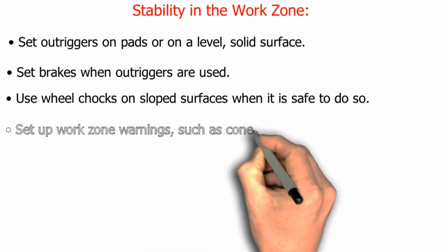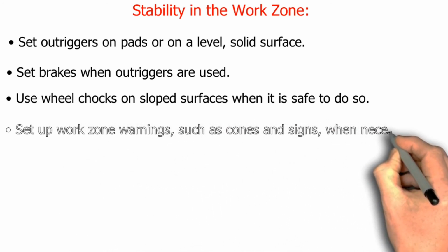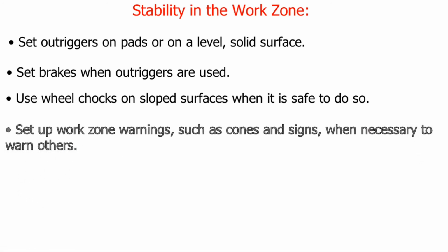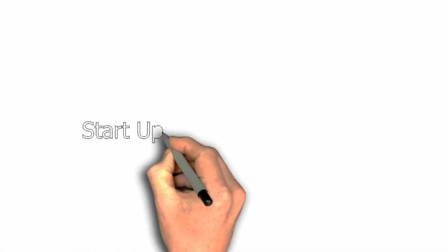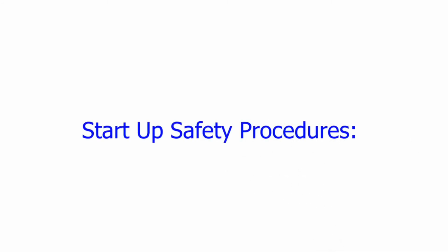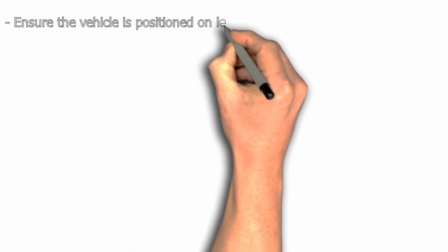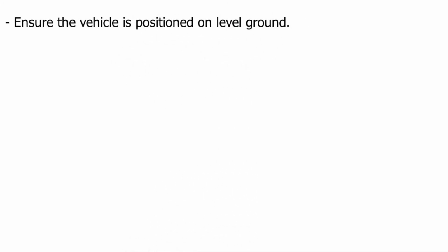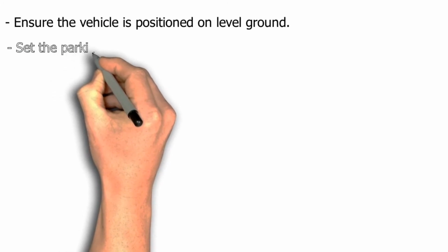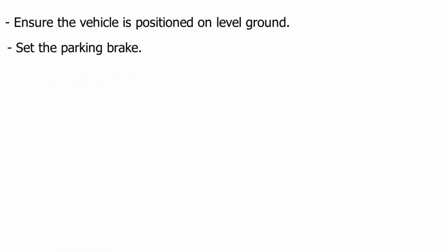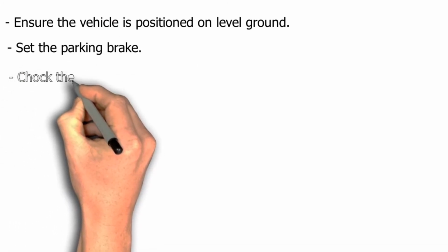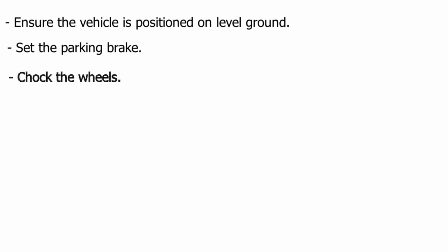Set up work zone warnings, such as cones and signs, when necessary to warn others. Startup safety procedures. Ensure the vehicle is positioned on level ground. Set the parking brake. Chock the wheels.